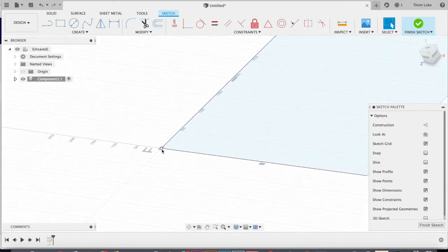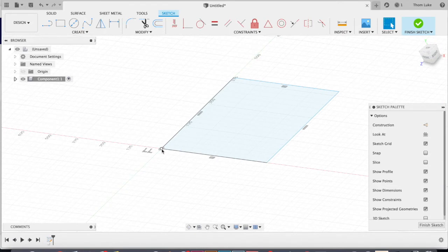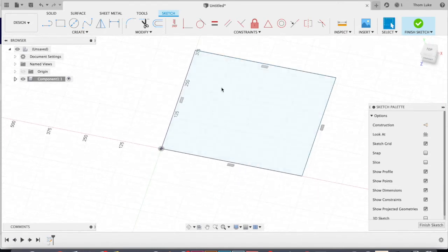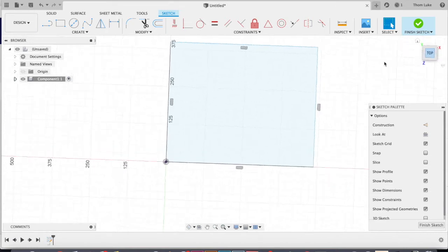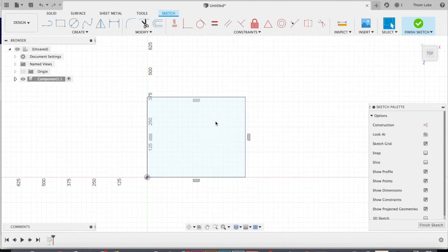The reason why this doesn't move here is because when I set the first point of the rectangle to the origin, I've essentially fixed it to that point, and that's called a constraint in Fusion. Constraints are really useful because we can build geometric relationships between things, and it's also an active control. The issue is that if we don't have constraints on something and we start building a really complex model, we might accidentally adjust something that wasn't constrained, and that can upset geometry and features downstream.